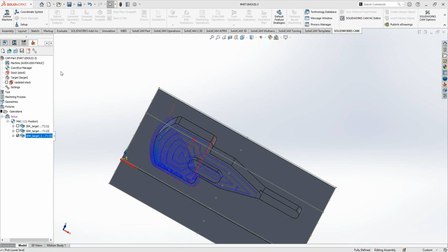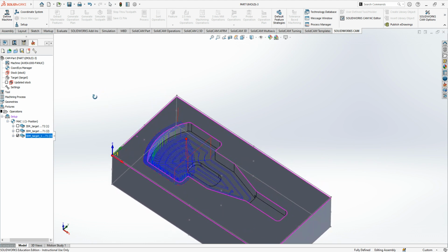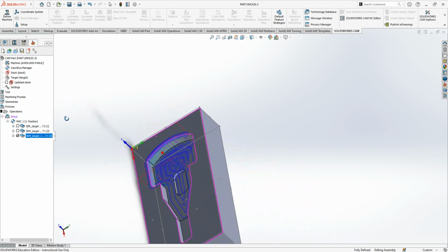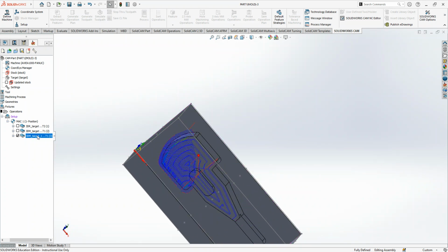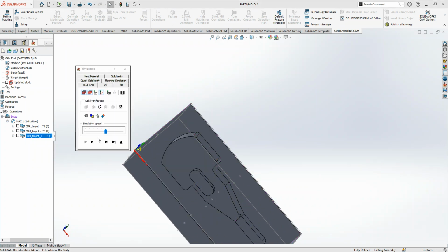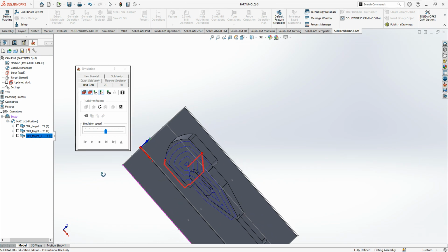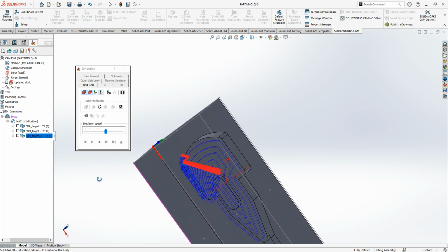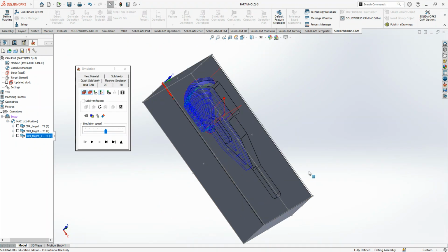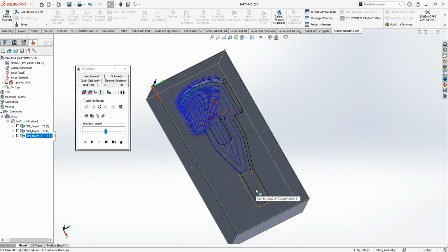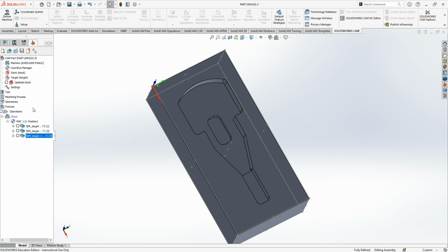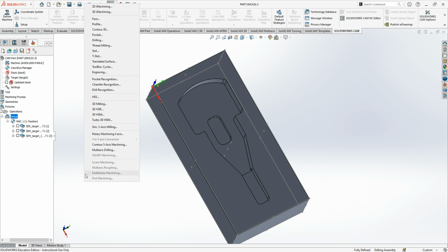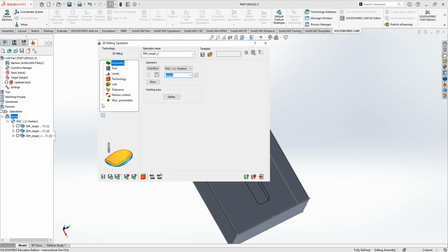I'm going to calculate the tool path. And we'll simulate. As this larger pocket has a deeper section than from the -10 setting when we took this down before, that looks fine. Once again, I'm going to add another milling operation, the final one, for the bottom pocket.